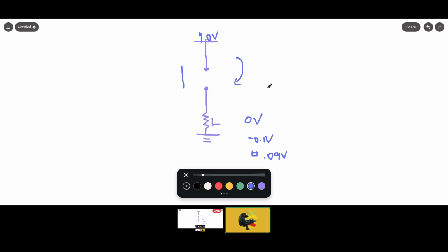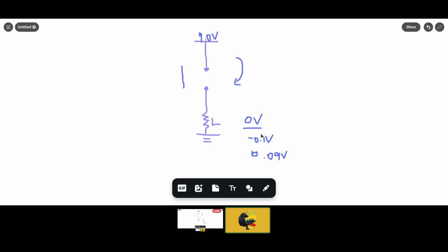There isn't that much of a big difference, but the difference can start to show when you're dealing with very, very delicate or digital circuits. For example, if you have a circuit for counting and you need to increment a decade counter, this inaccuracy of not having 0 volts when the switch is open could potentially cause issues in that delicate digital system. As such, it is not good.